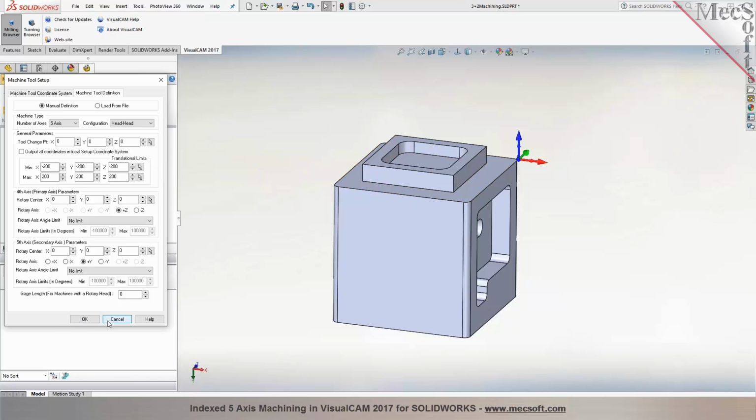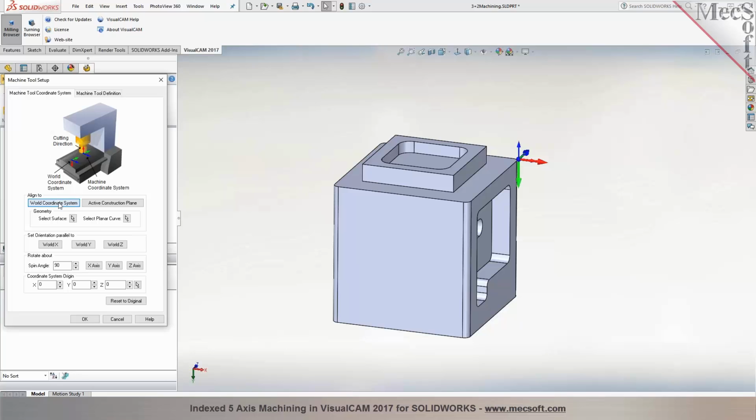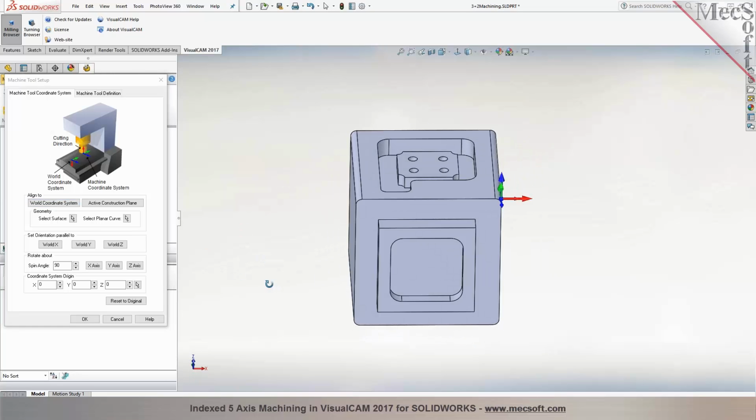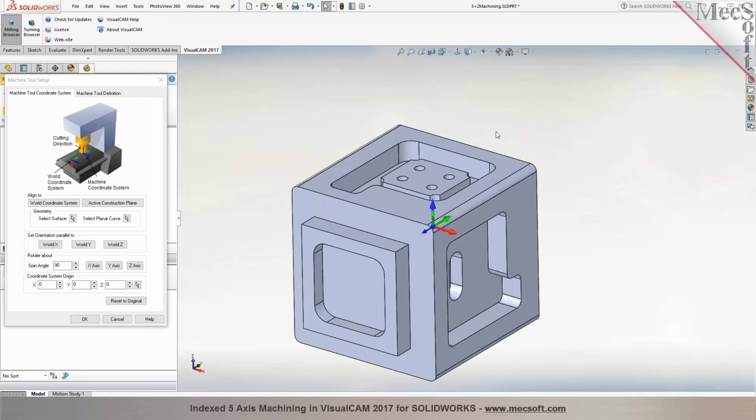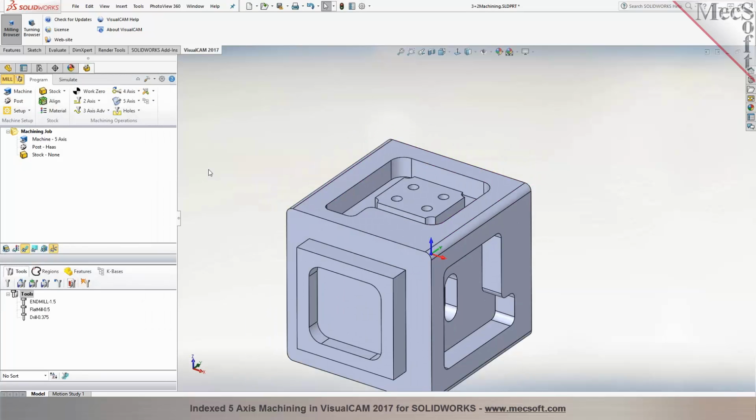So that's the reason why when you do 5-axis indexed or 5-axis simultaneous programming, you would want to establish your initial orientation, because even though you add a work 0, it'll first still go back and transform it to this position. Okay. Yeah, and that is so important. That's the reason, because it's so important to choose this position at the beginning of all the process. Right, because there's only one origin that you typically reference out of when you do 5-axis programming.